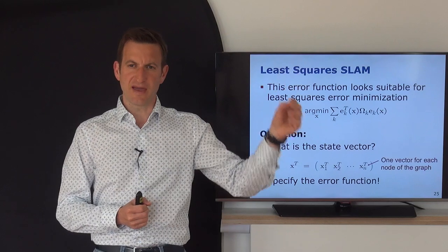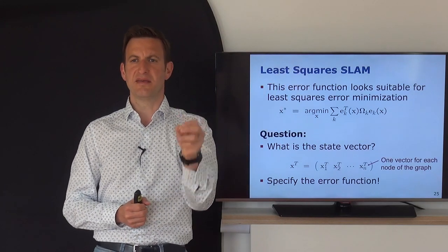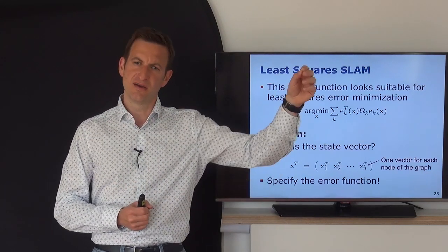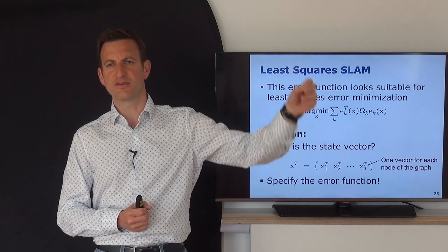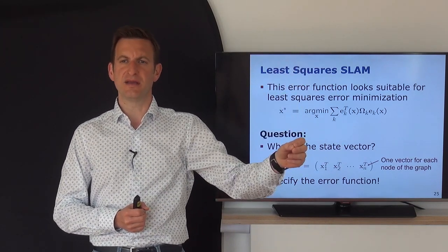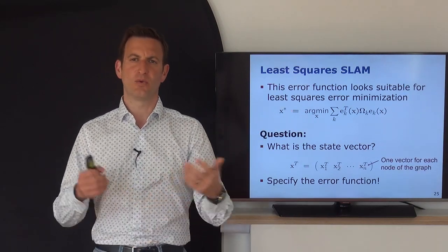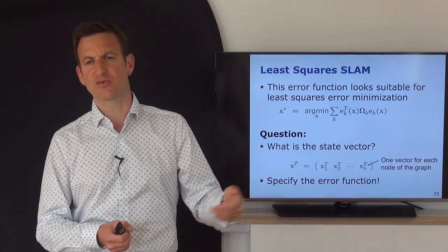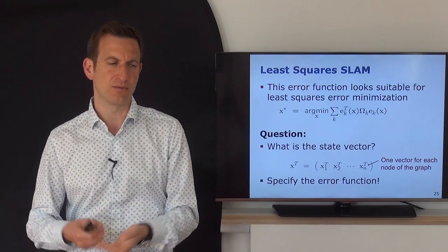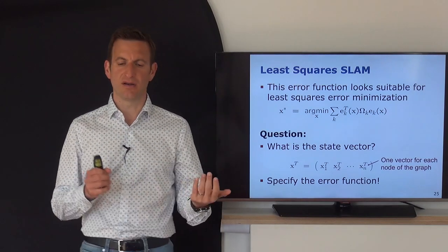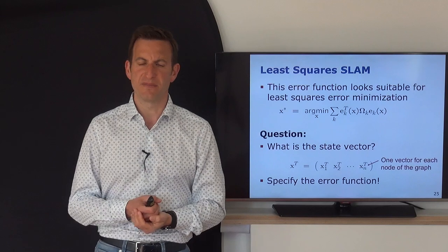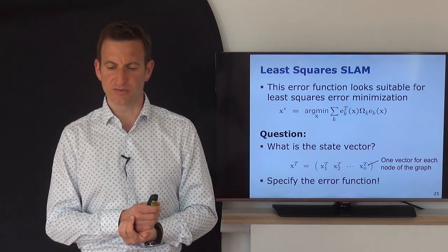It's always x, y, theta, x, y, theta, x, y, theta. It's always the x of the first node, the y of the first node, the orientation that the robot had when being there, and then for the second node, x, y, theta, and so on. Or, if you're doing a three-dimensional world, x, y, z, yaw, pitch, roll, for example, or another representation of the six-degree-of-freedom poses.